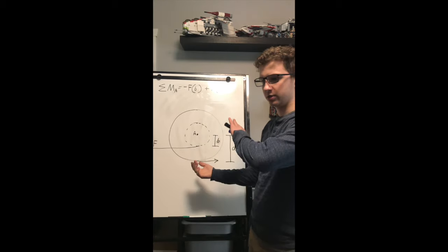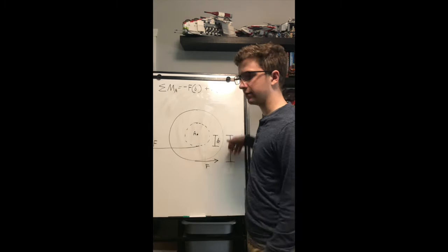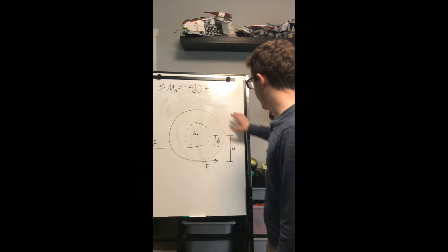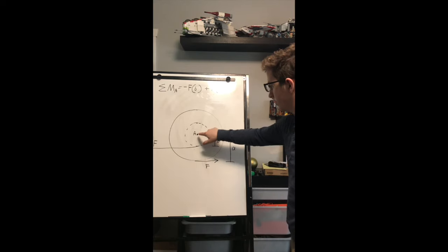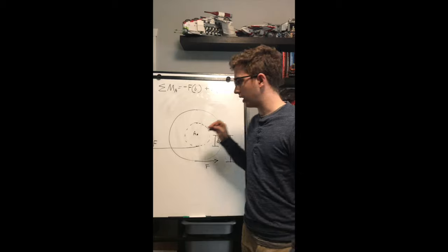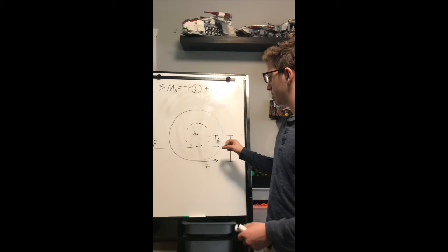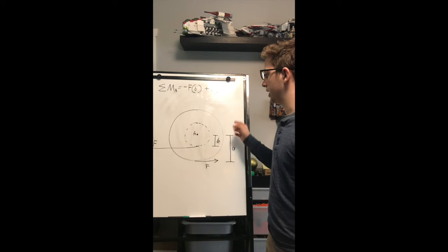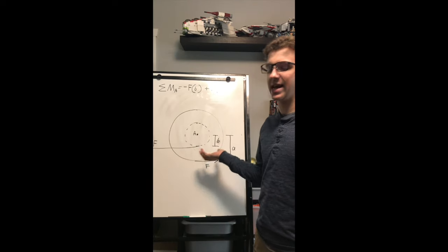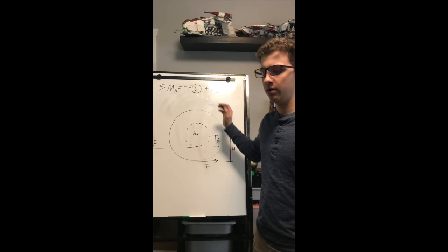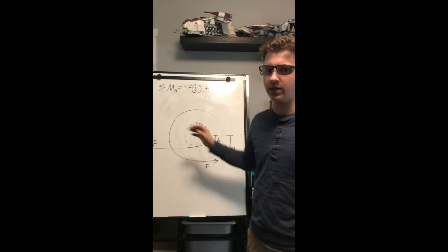The force trying to turn it counterclockwise, giving it a positive torque, is the same force times the distance A from here to here. So from this example, I hope it's clear that as long as B is less than A, it will always result in a net positive torque and therefore roll the system counterclockwise backward.